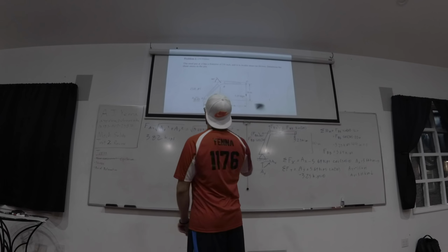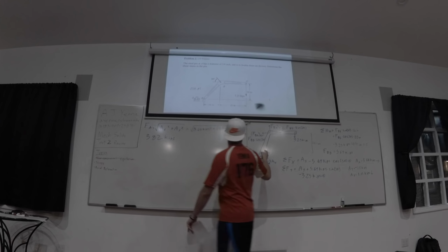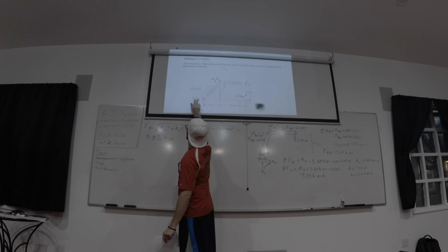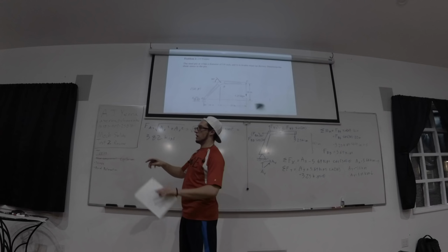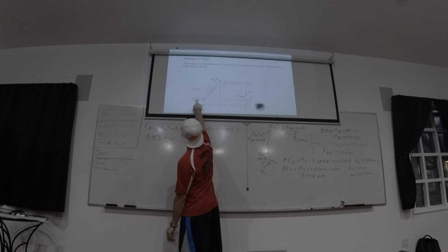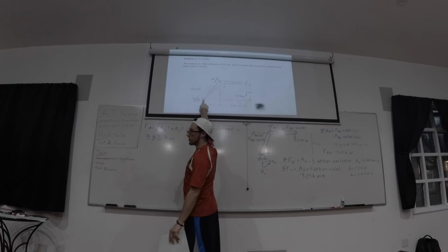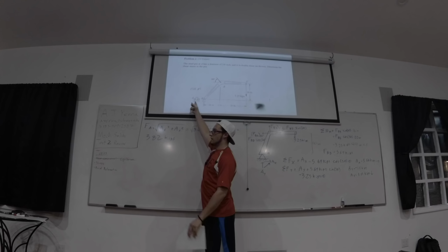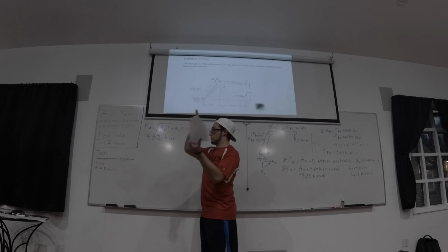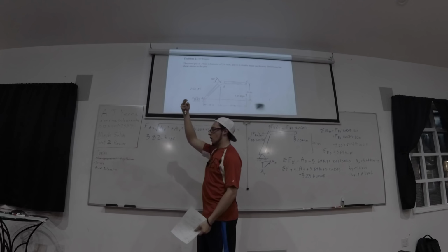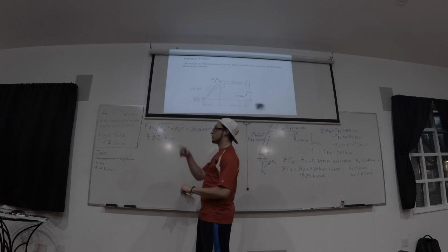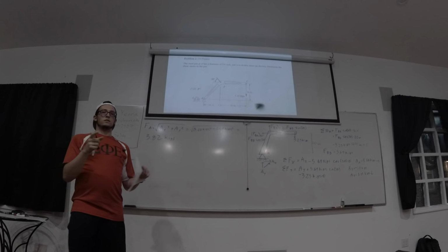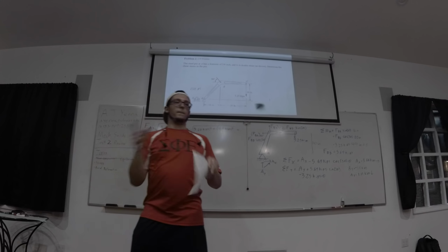But for this one, the shear force that they gave you can't be used to solve for normal force in this problem because of the way it's drawn and asked. Normal stress would be caused by a force along the pin, so this would have had to be drawn from a different angle, and they would have had to give you some force here, which we don't know. If you picture this from the side, you have a force going this way and a force going that way. Those are your shear forces, but they're both pulling across the pin. None of them are pulling along the pin. That's where you'd be getting into normal force, normal stress. All good? Anybody else? No. Okay.